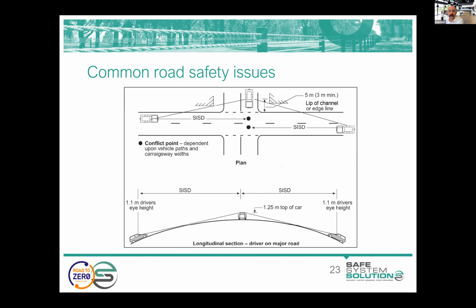Yeah, and so in Australia, it talks about rural environments and urban environments, and correct me if I'm wrong, Jamie. The idea being that in the urban environments you're expecting road users to be more alert, but in the rural environments, maybe not as quick to react. Is that right? Yeah, absolutely right. We often do adopt a lesser reaction time in the urban environment.